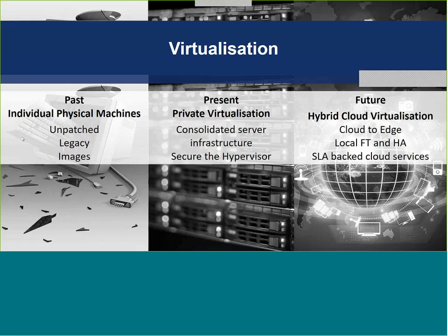Moving forward from here, centralized control is a key element to enable the scalability and flexibility required for a SCADA solution. Centralizing your software packages reduces the surface attack area and the devices you need to protect, and provides central management of your servers. In addition, you can reduce the number of physical assets to manage and secure, and it allows for easier incident and recovery plans. This approach also provides the scalability from line to site to enterprise, going from a single physical host to a clustered storage area network.